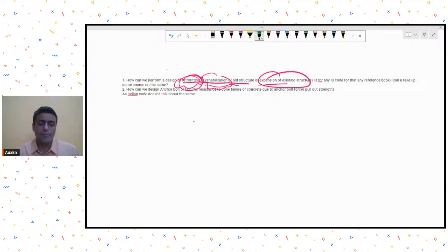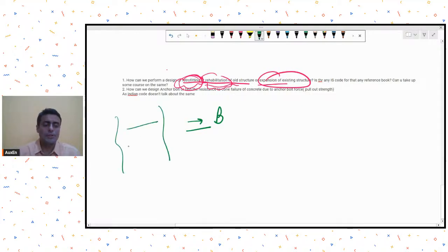So in all such cases, how you can do so, don't expect me to be able to cover it in 5 6 minutes, but the basic concept would be that the first step you should be taking is some visual inspection, and you should be collecting visual information, visual data as much as possible. Those visual data will help you to assess the condition and overall structural integrity of your structure. Condition assessment, you can do it visually.